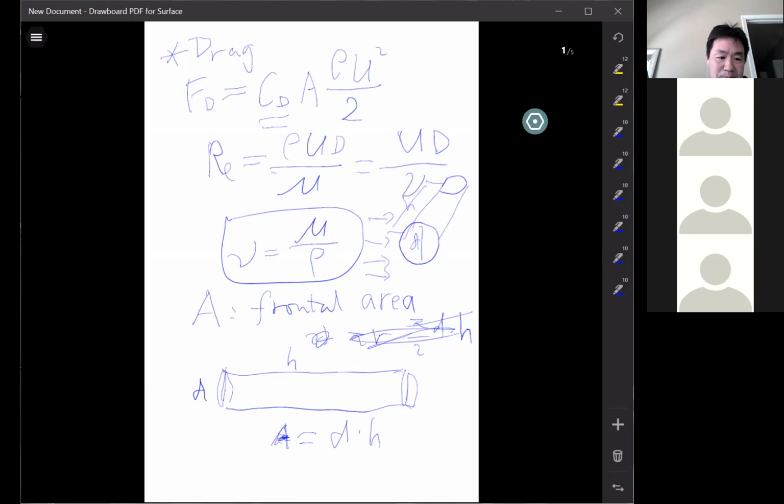So that's just diameter times the length of the whole pipe, or a certain section? It's a section of interest. In a real practical application, you're interested in a pipe when the flow goes across it, right? If it's outside the flow, it doesn't matter to you. So it'd be a specified length for the frontal area, like H, depending on the flow.